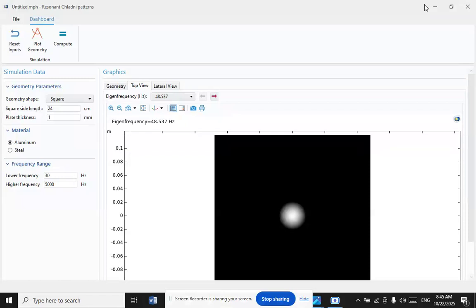Consider a damped mass on a spring driven by a sinusoidally externally applied force. Newton's second law takes the form m x'' + c x' + k x = F0 sin(ωt), where m is the mass, x is the displacement of the mass from the equilibrium point, F0 is the driving amplitude, ω is the driving angular frequency, k is the spring constant, and c is the viscous damping coefficient.